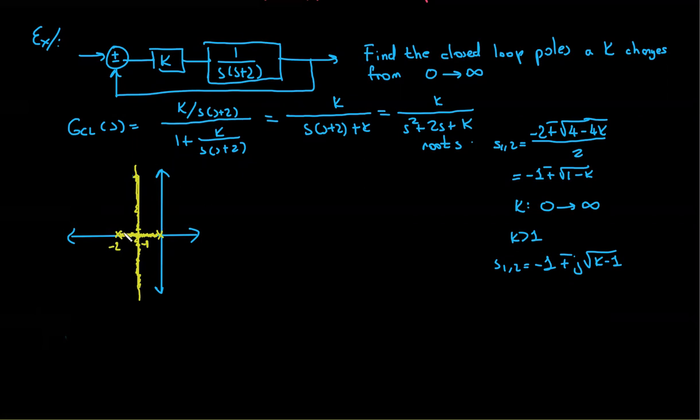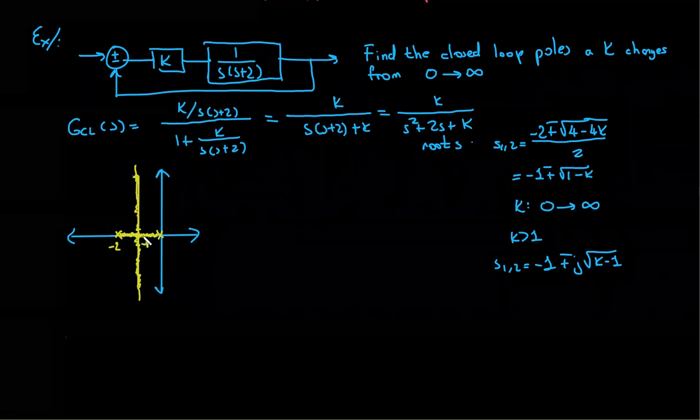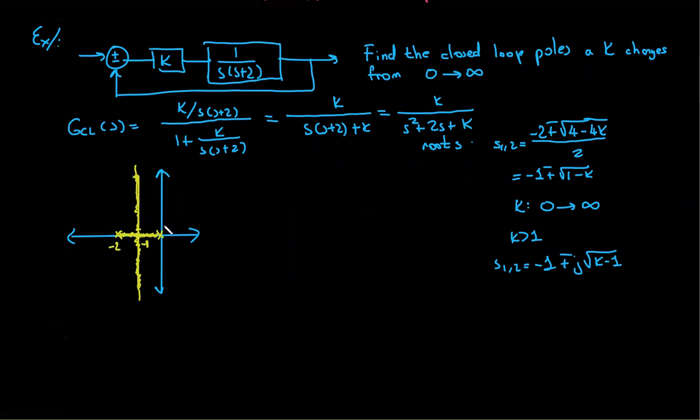So root locus is the trajectory followed by the closed loop poles when I'm changing a single parameter. In this case, it was the proportional controller gain k over there. The location of the closed loop poles changes, right, for each value of k. And the trajectory followed by these closed loop poles is called the root locus. Okay, so maybe I can try to write it down.